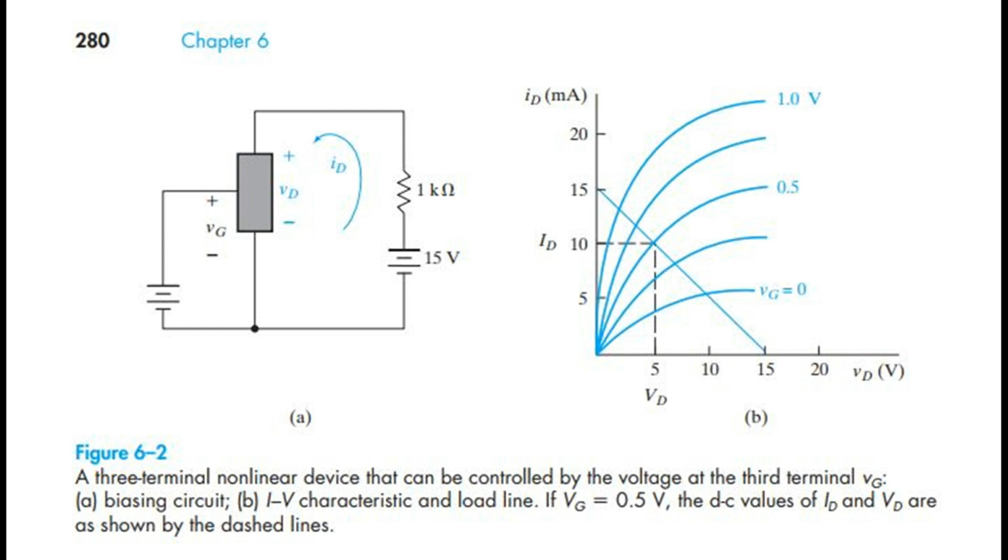This type of voltage-controlled amplification is typical of field effect transistors. For bipolar transistors, a small control current is used to achieve large changes in the device current, achieving current amplification. Another important circuit function of transistors is the controlled switching of the device off and on. In the example of Fig 6.2, we can switch from the bottom of the load line, ID = 0, to almost the top, ID = E/R, by appropriate changes in gate voltage. This type of switching with control at a third terminal is particularly useful in digital circuits.